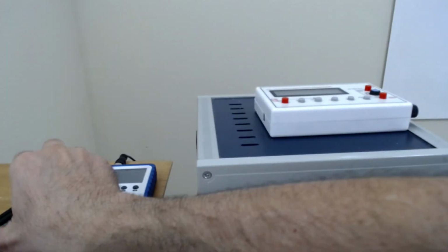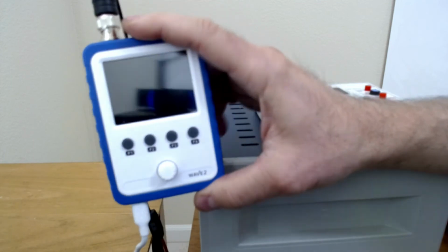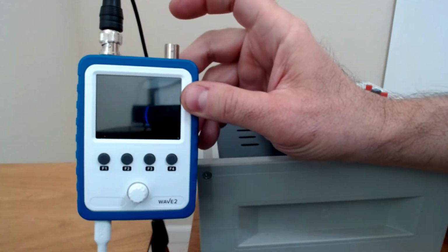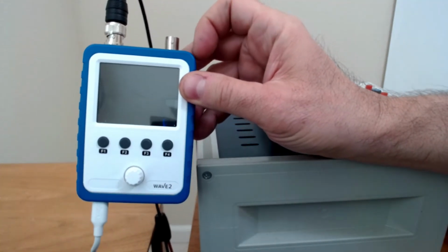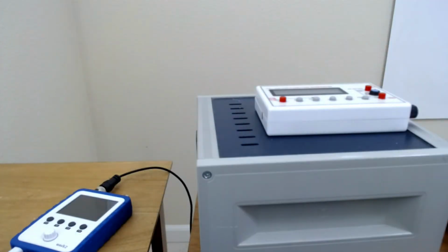This is not the ideal scope to use. The ideal one really for us to use is this one, because it has 2 inputs, so you can compare the power supply voltage to whatever you're measuring. You can look at shifts in your voltage, etc. But we're going to go with what we can get. So, all right, let me talk about triggering.